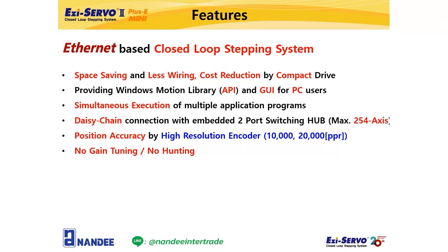In general, when controlling a stepping motor, motor heat is a problem because the maximum current flows regardless of the load, but since Easy Servo controls the current according to the load like a servo, it can relatively suppress heat generation compared to conventional stepping motors. We have looked at the features of Easy Servo 2 Plus E-Mini until now.